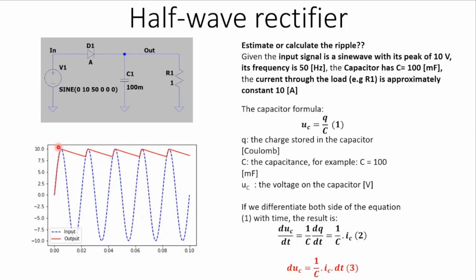First, let's look at the rectified signal again at the output. By the way, I just want to add why this circuit is called a half-wave rectifier. As you could see, when we have the AC input, the output is the red signal. If the ripple here is very small, the signal can be considered as DC, because the AC is rectified to be a DC signal. That's why we call the circuit a rectifier.